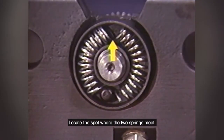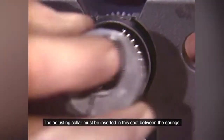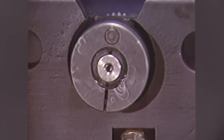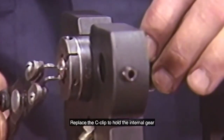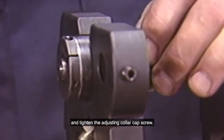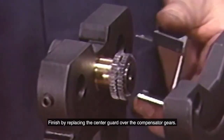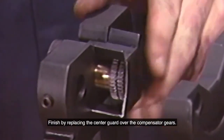Locate the spot where the 2 springs meet. The adjusting collar must be inserted in this spot between the springs. Replace the C-clip to hold the internal gear and tighten the adjusting collar cap screw. Finish by replacing the center guard over the compensator gears.